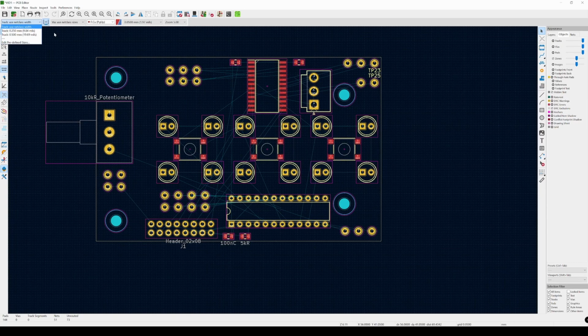And you need to realize that if you go to very small track widths, it's actually going to cost more than with wider tracks. And generally speaking, wider tracks shouldn't cost more, since PCB manufacturing doesn't really work that way, that the more copper you have exposed, the more it costs.